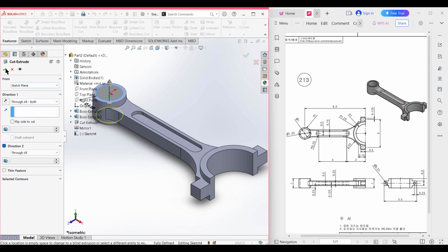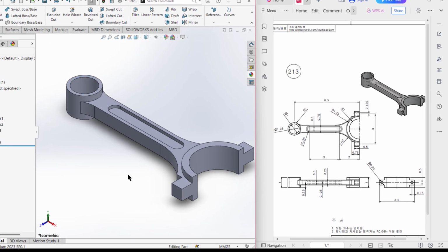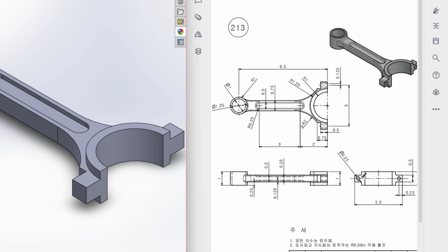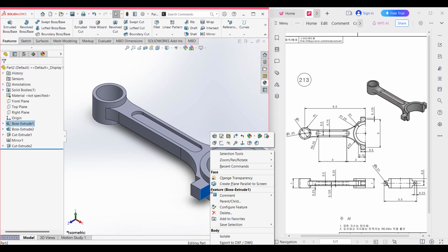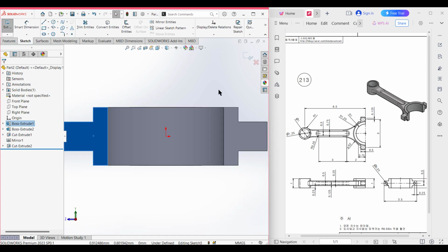Okay. Now press OK. Then if we look back to this right side sketch, we can see we have two circular cuts, and these two circular cuts have a dimension of 0.25 diameter. They are used to cut through all on this side and through all on this side. As they are situated in the middle, I'm right clicking on it. Now sketch. Now normal to it.